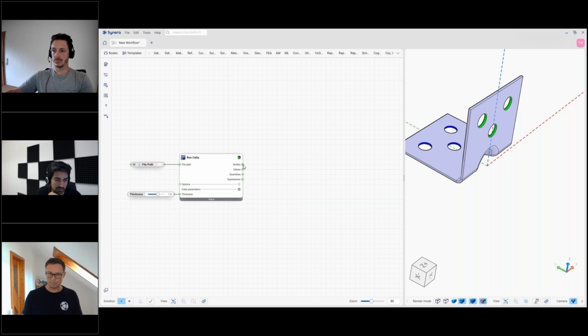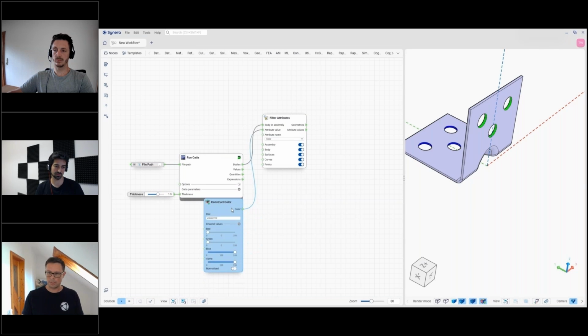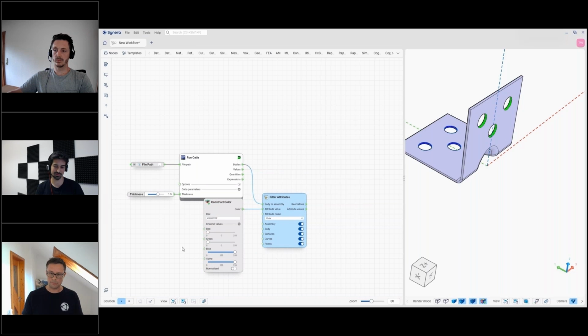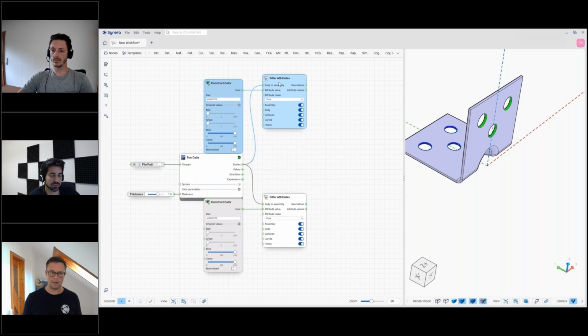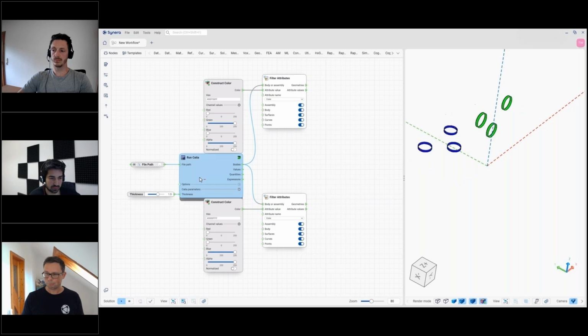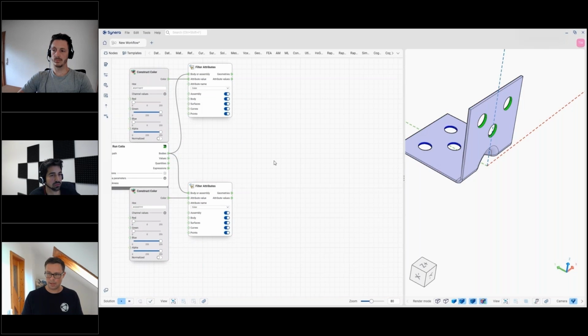Okay, in the next step, we will create a simulation model on it, and we will use the color-coded surfaces. Therefore, we have to extract the surfaces. And this color approach is pretty nice because this is then really geometry independent. If we import a different part next time, but it also has blue colored and green colored surfaces, the workflow will run through.